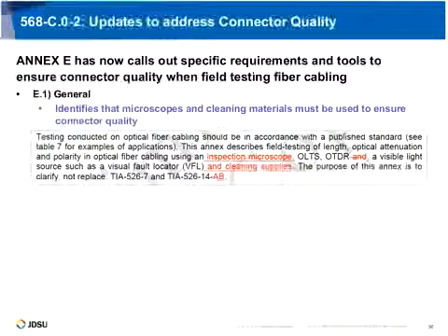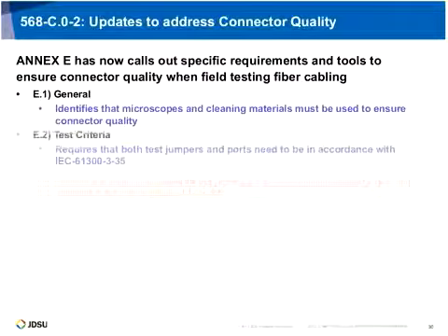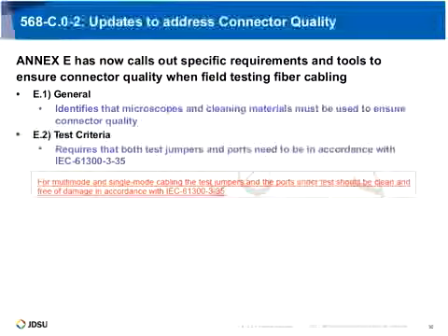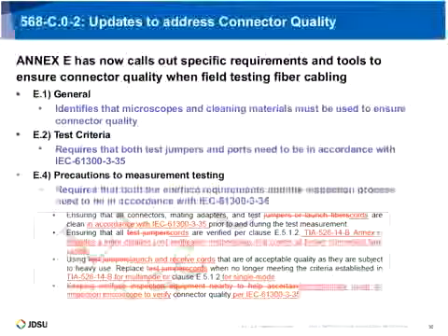You need to use the proper tools, and so they're clarifying that. They're also saying that both the test jumpers and the ports need to be in accordance with the IEC standard. And I just want to reiterate here, they're saying both the test jumpers and the ports. So that means your bulkheads and your patch cords. So don't fall into that trap of just making sure your test jumper's clean.